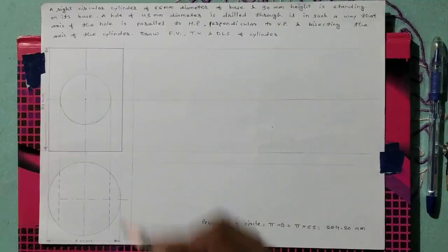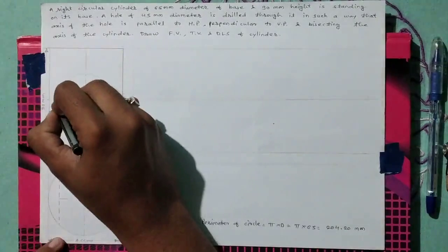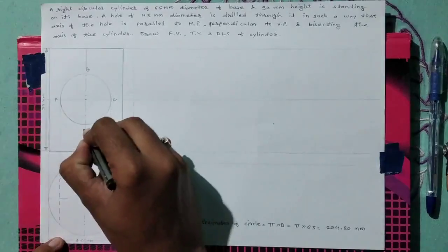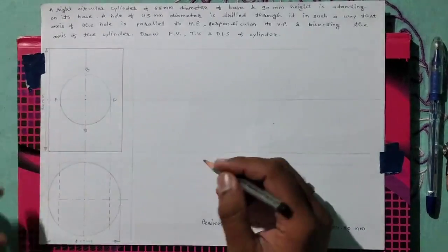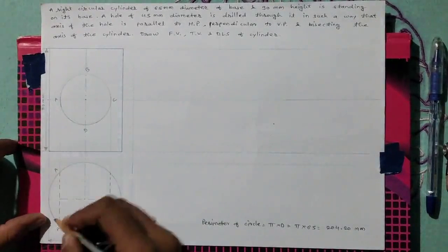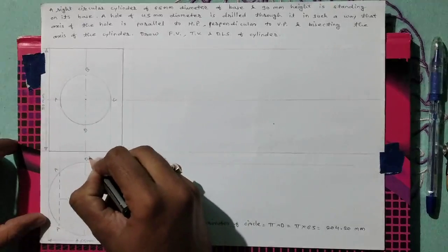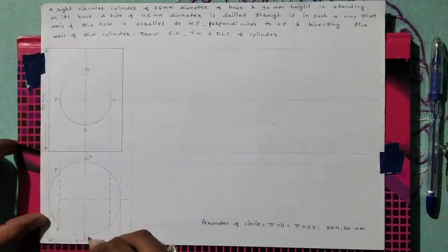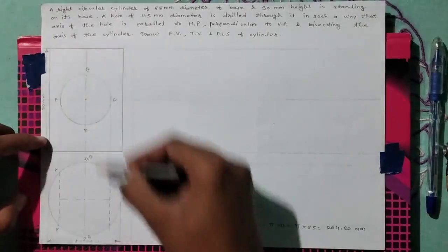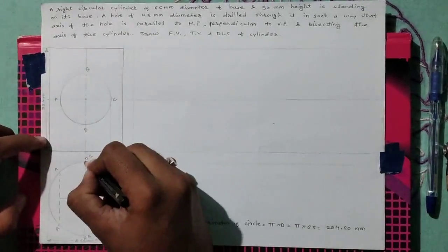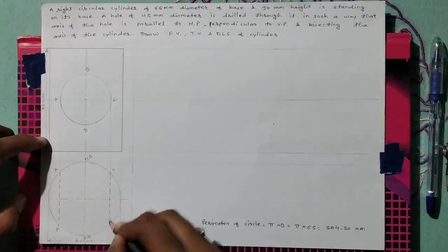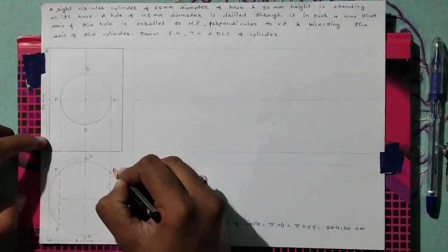After that we have to give the names in the front view as A, B, C, D, and take these names in the top view. The A point will be here, A and here A. After that D, B, where these projection lines intersect the profile of the top view. At that intersection point we have to give the names. The C point will intersect here, therefore we put this name as C.